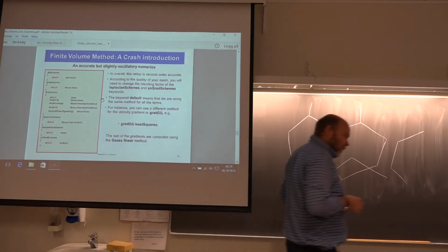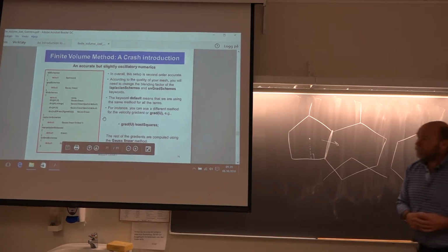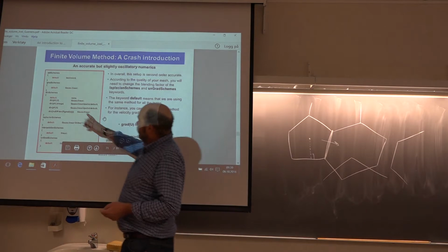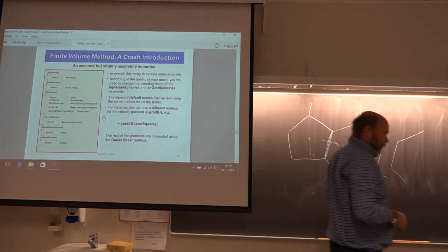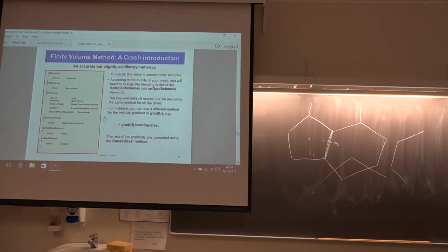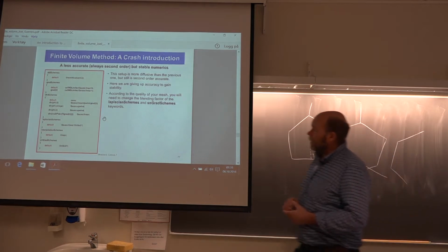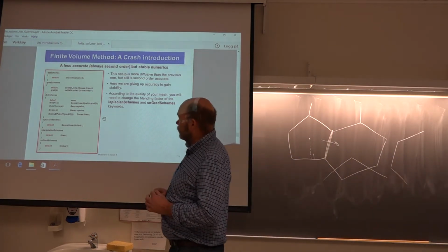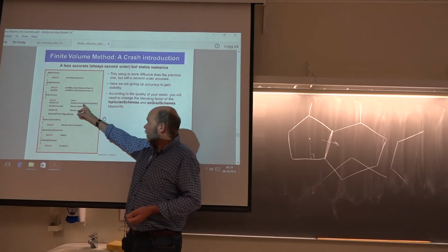So yeah, I would say very jumpy scheme he has chosen here. And the main problem then is this one, phi U, linear. That's a central scheme, dangerous. Less accurate, but quite stable. Okay, you have gone to a linear upwind.